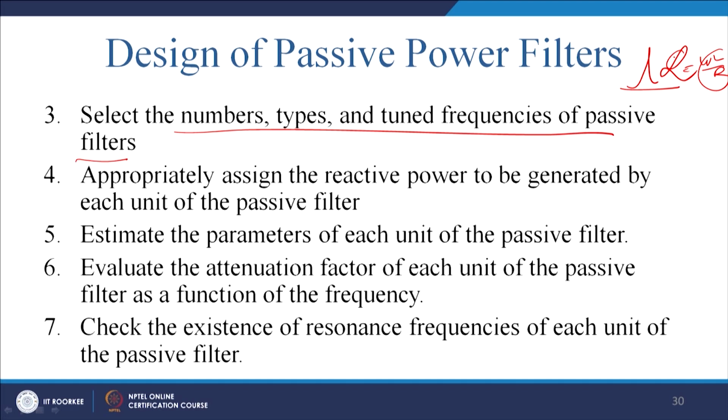But generally what happens is, if you have a very sharp notch, then the value of Q required is higher. If the value of Q required is higher, then omega L by R will be high, and thus you require to reduce the value of the resistance. Since you cannot do anything with the value of the inductance, and the capacitor value is already fixed, you require to take a higher gauge wire. For this reason we generally try to compensate like that. It is, to some extent, the optimized solution.